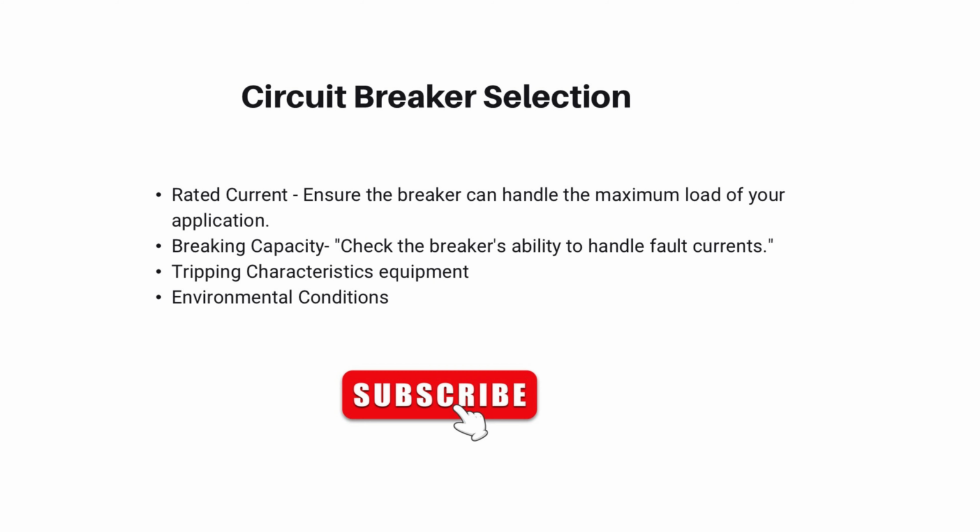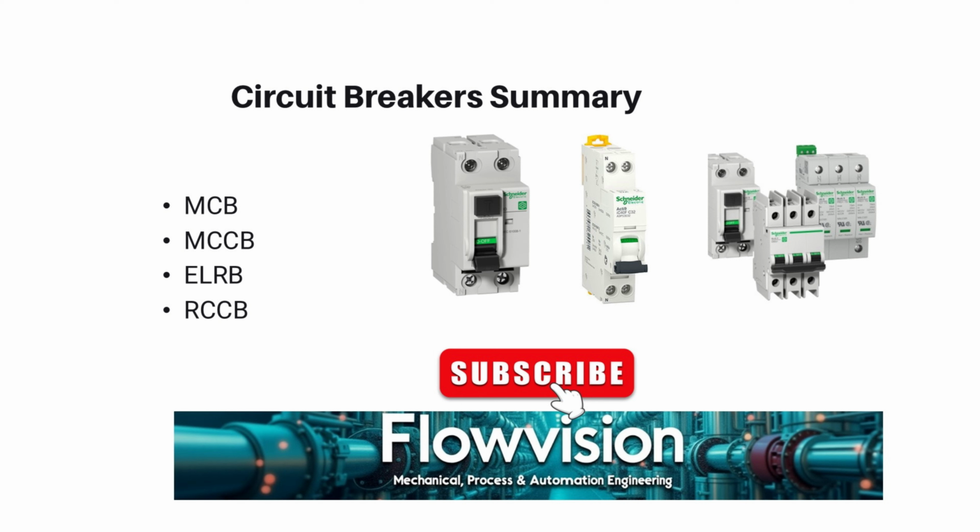Lastly, for installation and maintenance tips, always ensure power is off before working on any electrical equipment. You need to follow the manufacturer's guidelines for installation procedures and also test the tripping mechanism periodically to ensure it functions properly. And that's a wrap to our guide to circuit breakers in control panels and industrial automation. These devices play a significant role in maintaining safety in electrical systems.